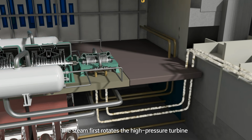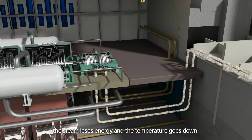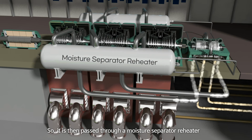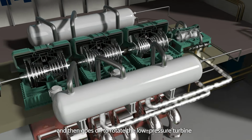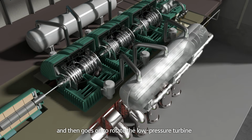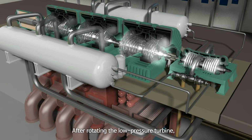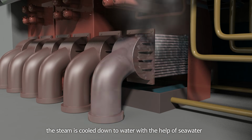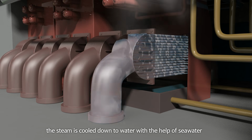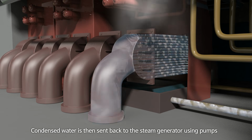The steam first rotates the high-pressure turbine. After rotating the high-pressure turbine, the steam loses energy and the temperature goes down. So it is then passed through a moisture separator reheater, which raises its temperature again and then goes on to rotate the low-pressure turbine. After rotating the low-pressure turbine, the steam is cooled down to water with the help of seawater. Condensed water is then sent back to the steam generator using pumps.